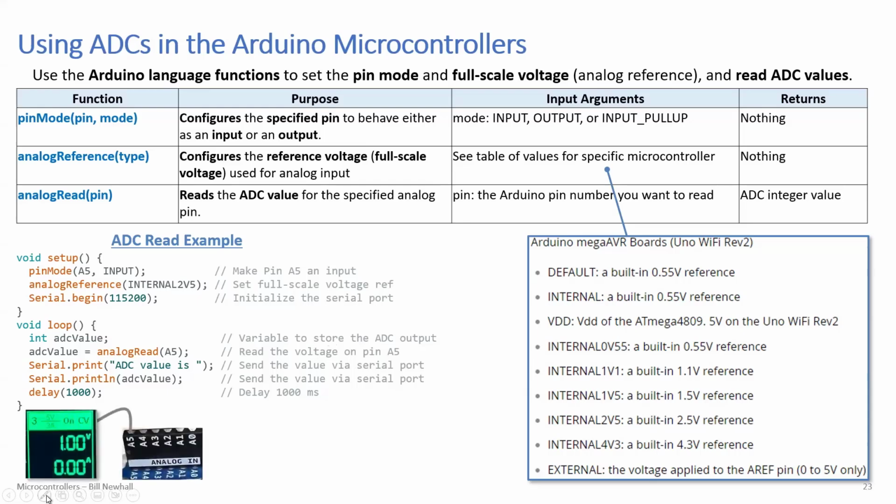So I took this code and I ran it. I applied a power supply voltage of 1 volt to pin A5. And I ran the code and I could see the ADC value right here. So you get 432, 432, 430, 429. It looks like there's some noise or it's varying a little bit.